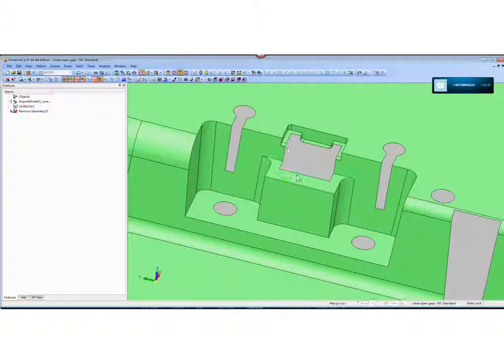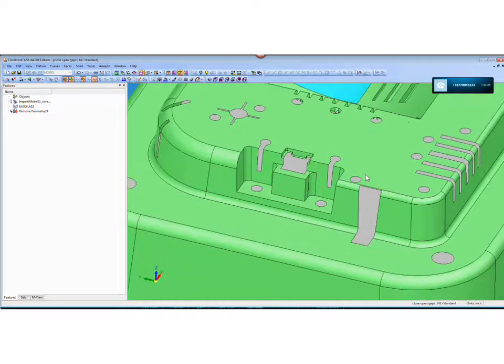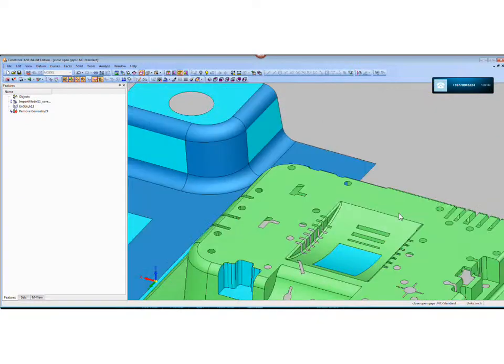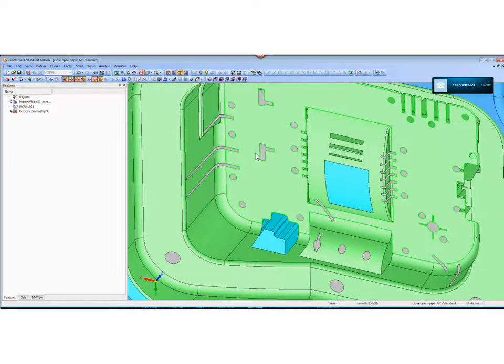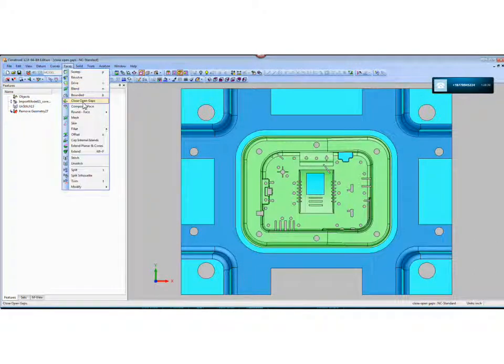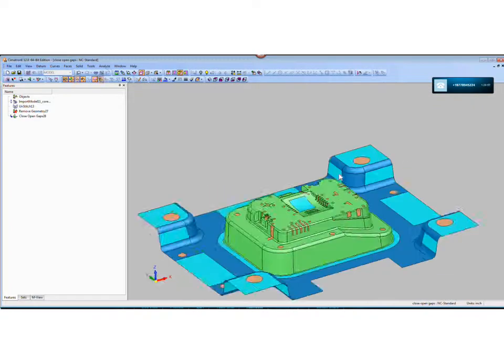And if I told you that the webinar wasn't going to end until all these surfaces were patched, guys would probably start exiting quickly. But watch this. I'm going to go to the top view and go to faces, close open gaps, and pick all this stuff. And I can do new faces or same faces. I want same faces. And I'm going to close up all these holes in one operation. So everything you see in brown was just created automatically.